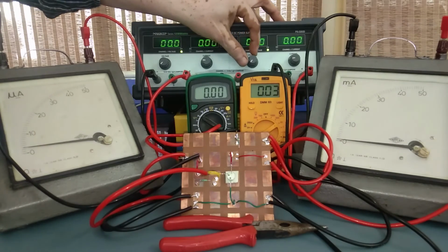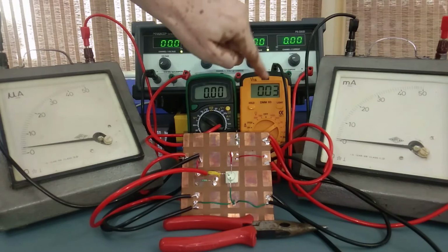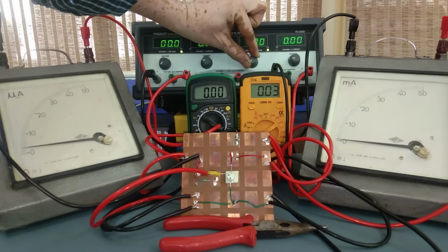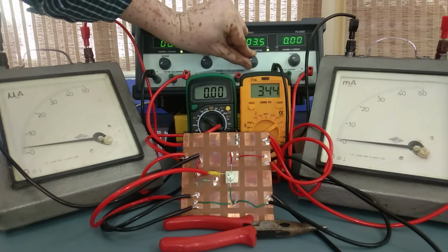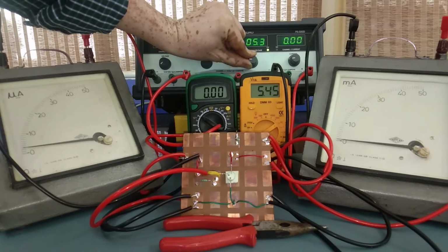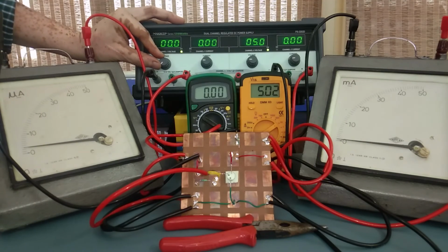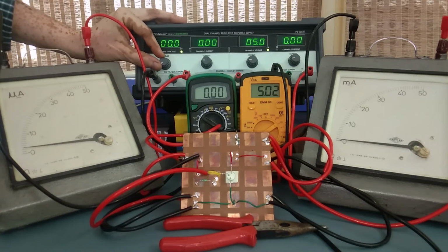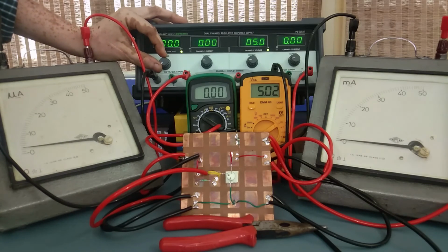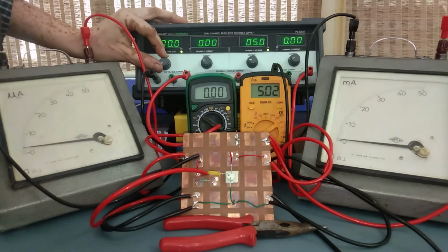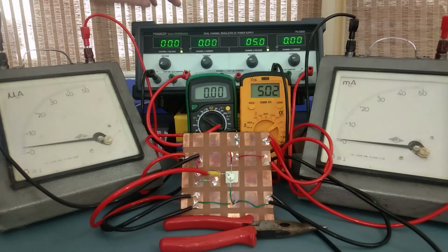So we will make here the VCE. You can note here the VCE at 5 volt. Okay, 5 volt. Now again we will keep on increasing the VBB and see what actually happens. You have to note this and this reading right now, because VCE right now is constant. So initially you can find VBE is 0 and there is no base current.